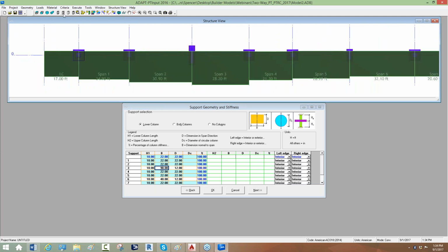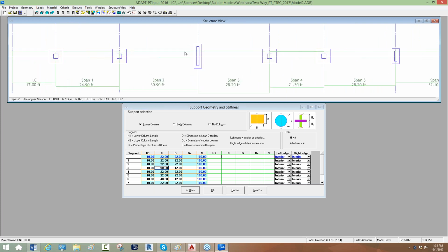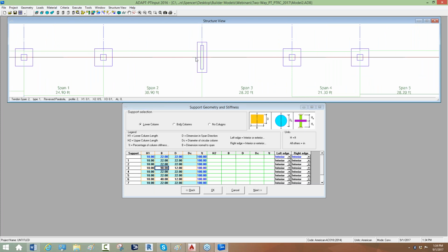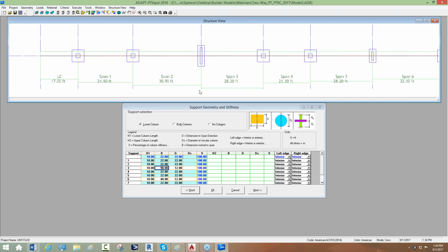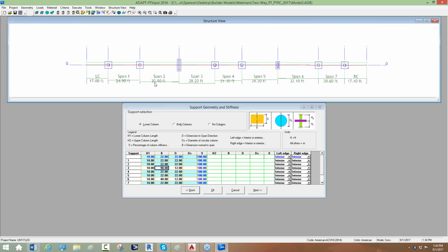And this is easier to see if I go to a shaded view. You can see there's the wall there, there's my center line, and so this is just discretized as a column, not an actual wall that's extending out of plane. So you want to try to model the wall to simulate the actual stiffness of that support that's there. I'm just arbitrarily using 48 inches just to give it some length that's different than the width of the column.